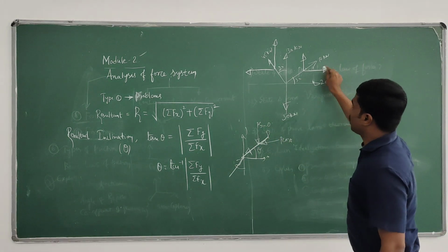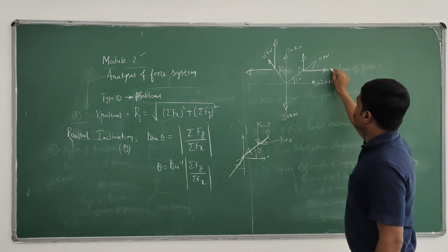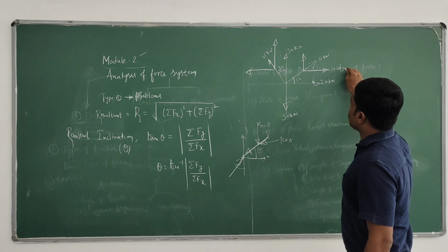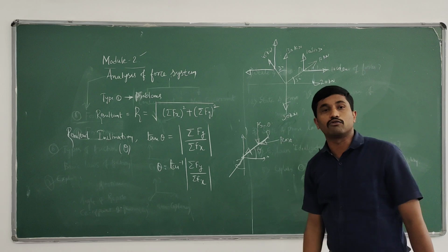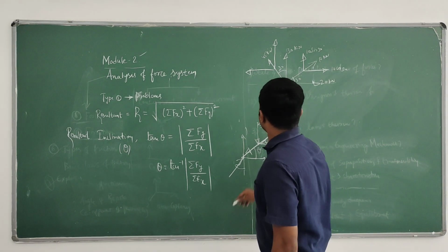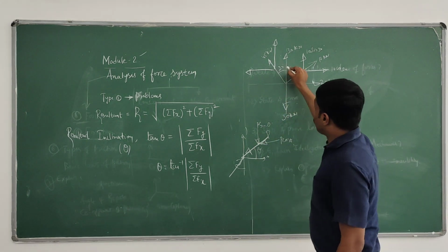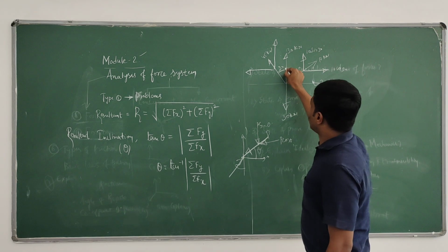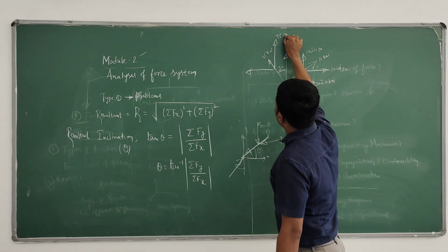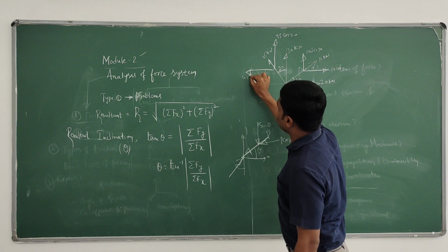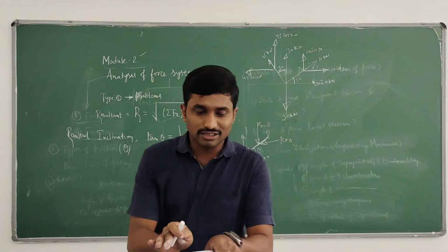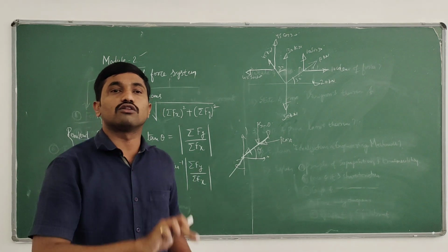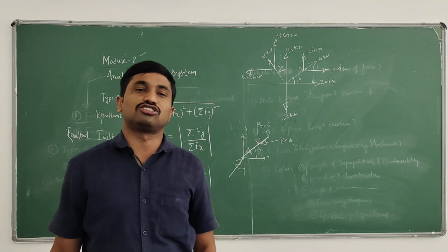Similarly, apply the same thing. The force is acting away. Therefore, this is 10 cos 30 and vertical is 10 sin 30. Similarly here, the vertical angle is given. Therefore, the vertical is cos theta, 45 cos 20. The remaining is 45 sin 20. That's all. That is the easiest way to remember how to resolve the forces in a two-dimensional system.